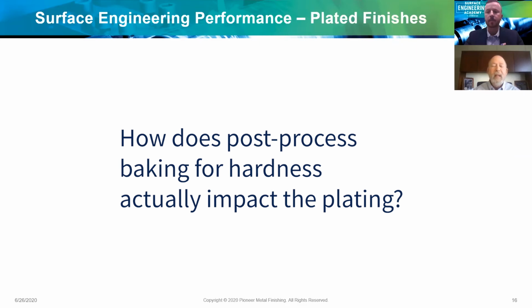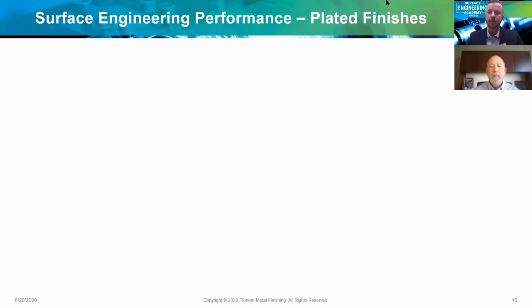Yeah, and again, as I mentioned, you really want to be careful with hardness bakes. The only reason to ever implement a hardness bake is if you had pure wear resistance as the desired outcome of your plating system. Yep. Okay, next question coming in.